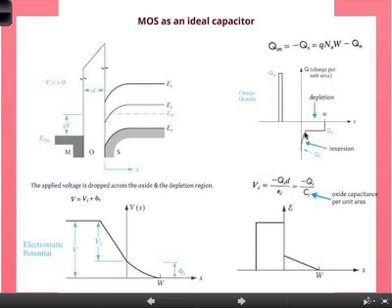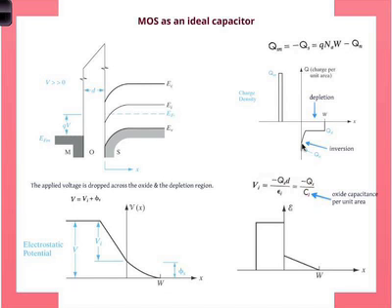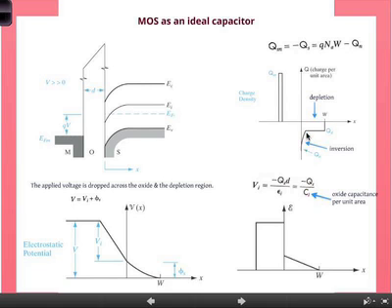So remember that the electron current flow is out of the plane of the screen. Okay, so now we're looking at a cross-section of the MOSFET to some extent, right? Then we have a depletion region here, which is basically fixed ions, the acceptor ions in this case, in the P-type material. Okay, and the whole thing has to cancel out, so this should be equal to this in terms of charges. The whole thing has to be neutral.